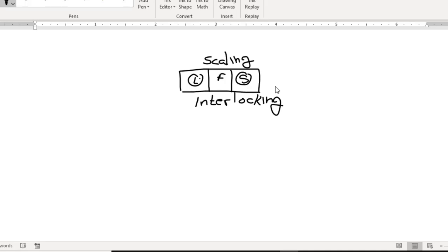So that's how that would be selected. And if this one was selected, it would create a value of 0. If this is selected, it would create a value of 1. If this is selected, it would create a value of 2. And those were the values you saw in the equal instructions. So they were coming from the HMI.